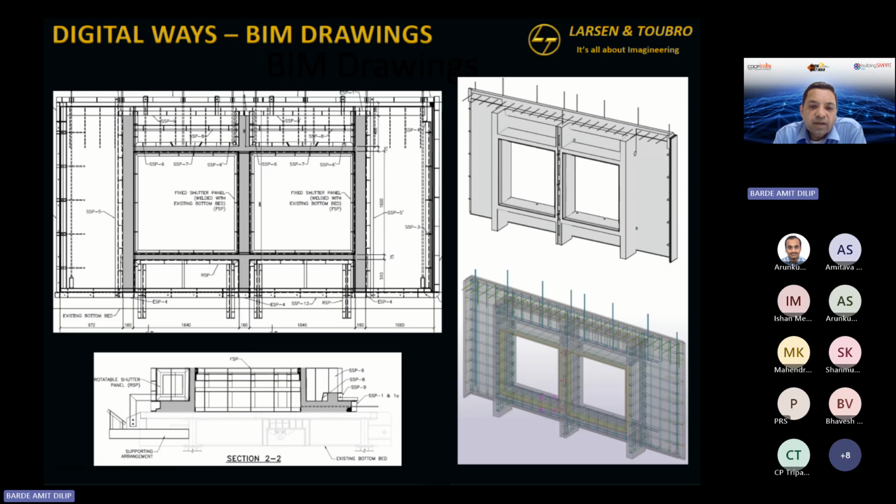The down left is my mold drawing. So we are generating the mold drawings also through this BIM model. Again, I noted about the concrete, there is much less manual intervention from batching plant to shuttle to mold. Here it's BIM to mold drawing to shop drawing and fabrication. Much less manual intervention, which is where the errors happen, in the dimensions and all. You perfect your BIM model and everything is linked. Productivity is one, but the errors are also much less.